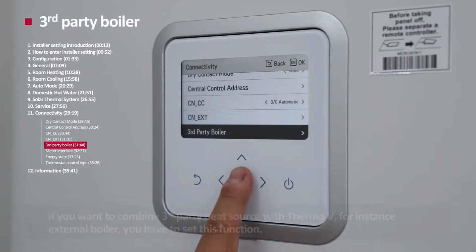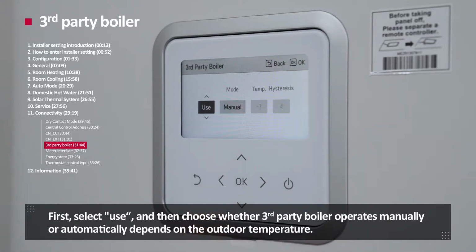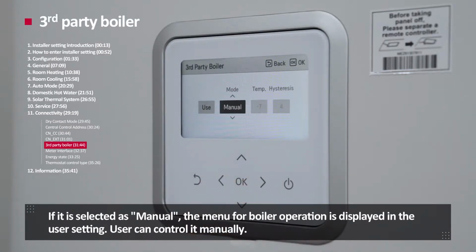Third-party boiler. If you want to combine third-party boiler heat source with Therma V, for instance, external boiler, you will have to set this function. First, select Use, and then choose whether third-party boiler operates manually or automatically, depending on the outdoor temperature. If it is selected as manual, the menu for boiler operation is displayed in the user setting.